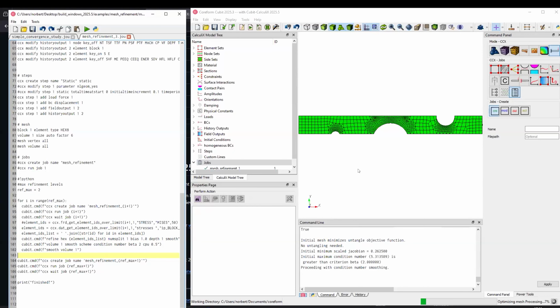That's the first refinement based on results. And that was the second. So here we are accurate enough, here not. So I took a second refinement step. Okay, that's the smoothing operation. Yeah, you can do something like that with the Python API if you have access to your solver in a way, or you can read in your results, even if they are written as CSV, because with Python, you can read that in also.